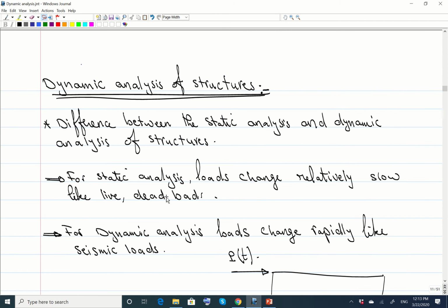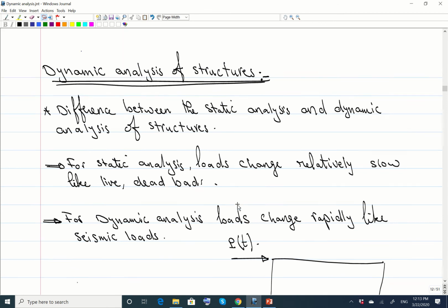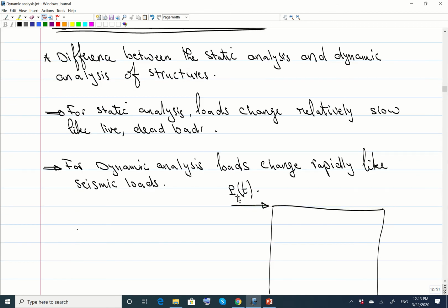On the other hand, what we're going to be doing in this course, an earthquake loading, is not a static force. It's a dynamic force, and not only a dynamic force, it's a dynamic force that changes so rapidly. Seismic loads change so rapidly. Wind loads, we don't assume that wind loads are dynamic loads, because yes, they are changing, but the rate that they change by is slow.